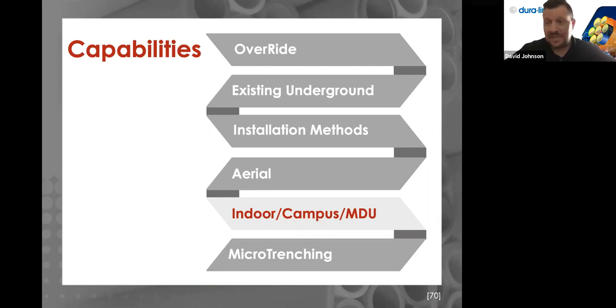But once again, it's a hard question to answer, but that just kind of lets you know, we tested AFL's fiber, we tested all the other fiber manufacturers when they came out with new products at that test track, and we're successfully blowing through 4,000 feet in multiple 90s with no issues. So that's just the extreme.